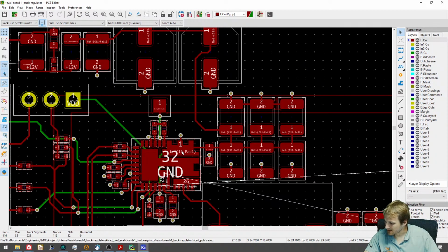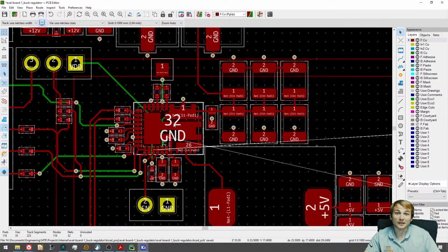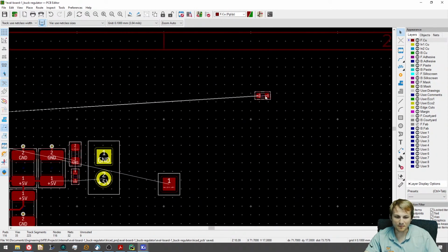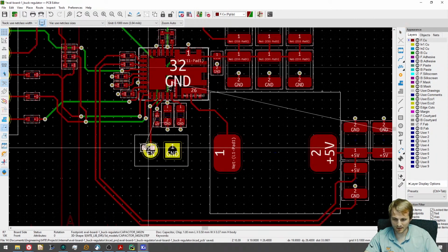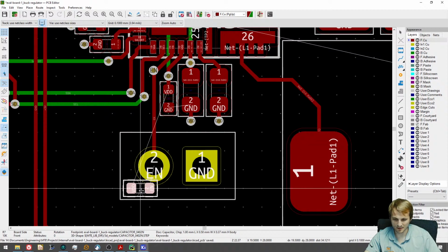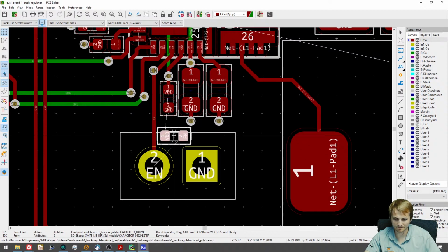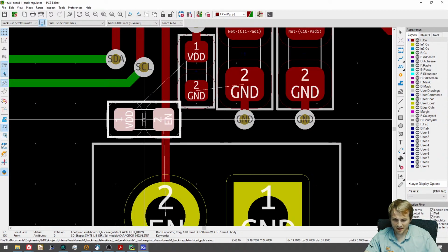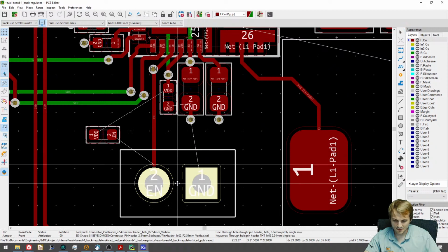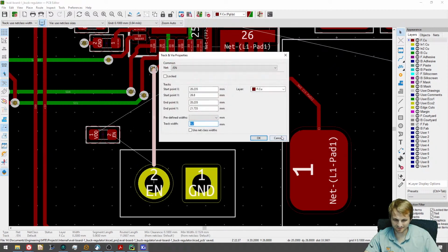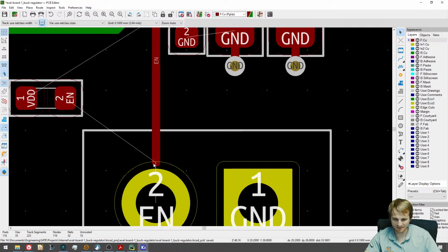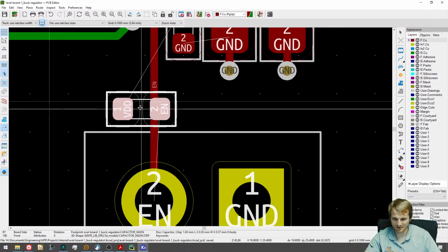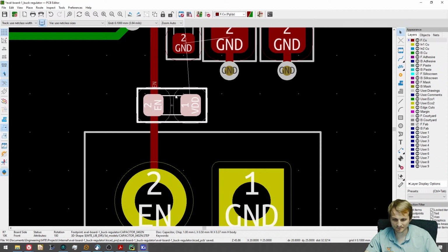Is there a special reason why you keep the pad output wire always straight? So I would like to say there's some amazing reason for it, but pad entry is mostly because it looks good. Back in the day, there would be a big issue with acid traps, but that really hasn't been an issue since before my time of doing layout. So it's just one of those things that's still done as a standard, but no, there's really no reason.